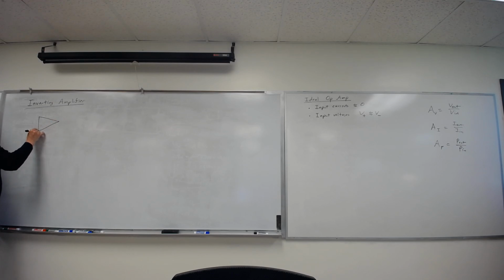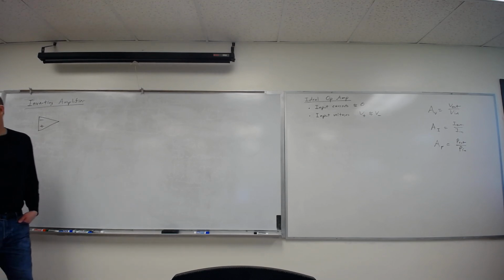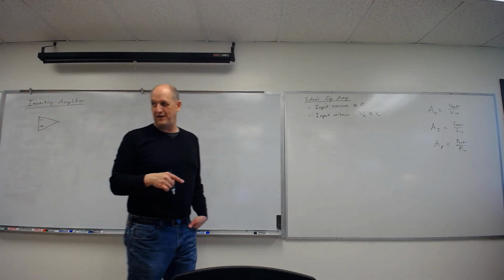I'm going to go into the inverting input. Be aware, there is no standard for which is the top and the bottom for the two inputs. You have to look at the labels. There's also no standard whether you draw the input into the top or the bottom, so you have to look at where the input comes from.